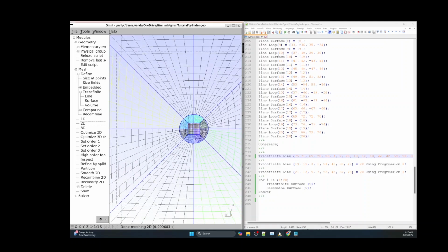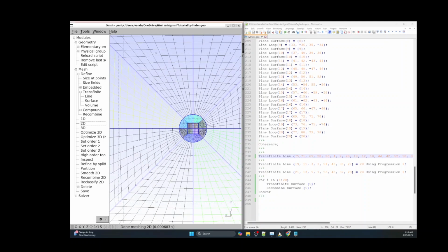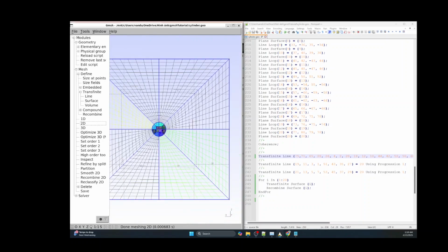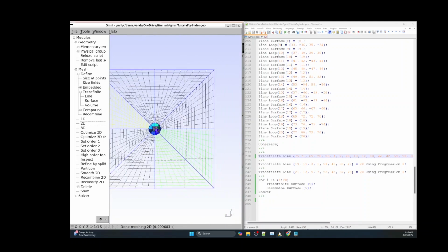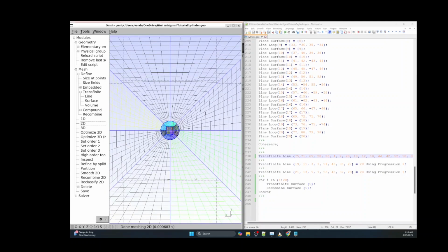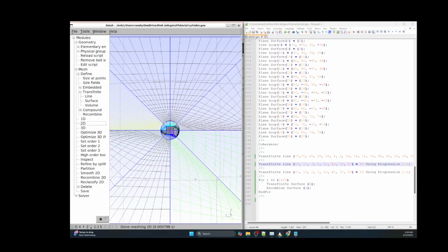But in reality, in our simulation, we need a fine mesh in the region we want. The reason is the interaction phase between the cylinder and the internal field, right? So we choose the line we want to have a progression. So I can change the 1.2 here.